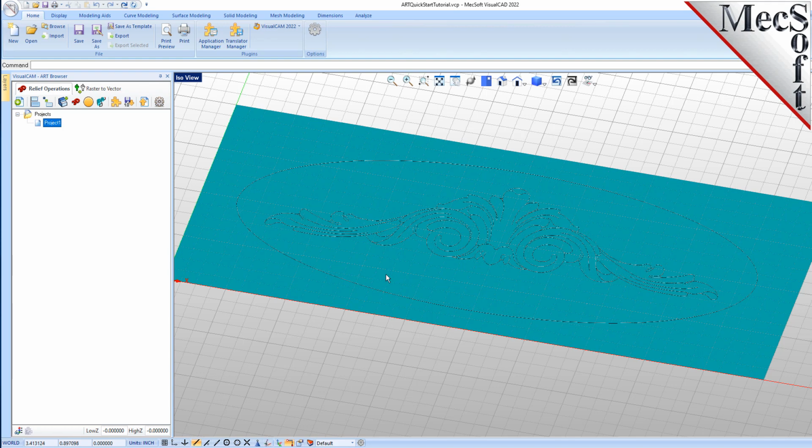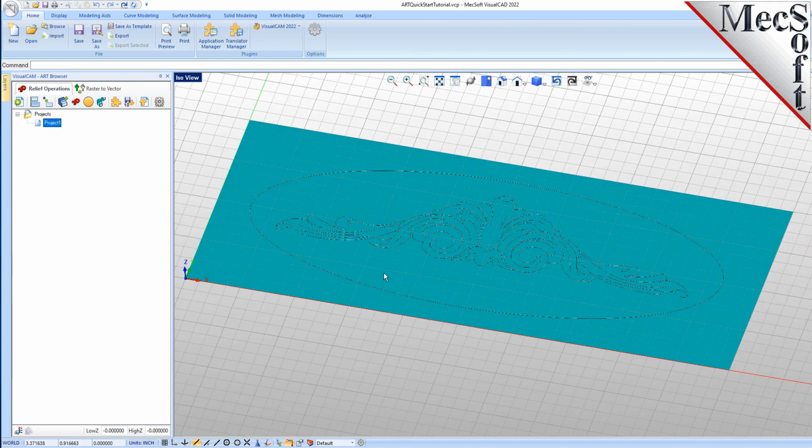Our first operation will create a swept volume. The Create Sweep operation allows you to sweep a cross-section shape along a selected rail curve to generate a swept volume. This function is typically used to create borders, highlights, and even 3D text shapes.